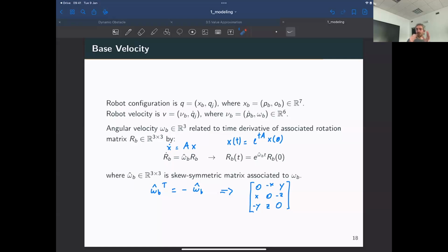And so there is a threshold: if you need to rotate a certain number of vectors and you have a quaternion, if the number of vectors is sufficiently large, it's better to convert the quaternion into a rotation matrix and then just apply the rotation matrix. But if the number of vectors is sufficiently small, it's better to directly apply the quaternion.